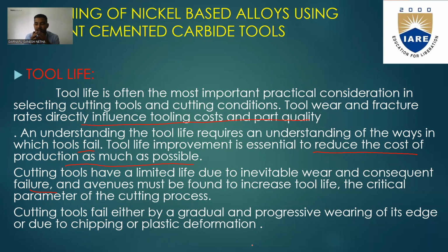You need to keep these few points in your mind. The first point is that the hardness of the workpiece material should be less than that of the cutting tool. The second point is that the speed of the cutting tool should be medium, the depth of cut should also be medium, and the chip removal rate should also be medium.